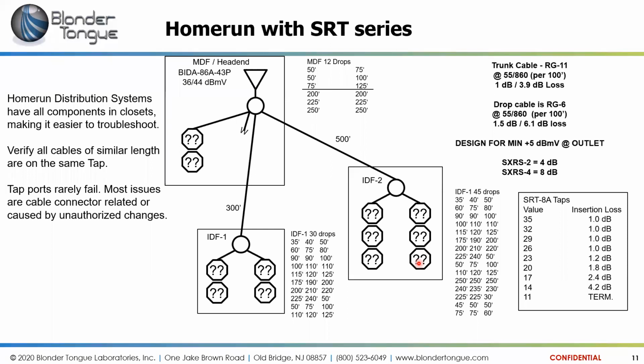For off-air antennas, what are typical RF levels into a pre-amplifier? Oh, with off-air antennas, there is no such thing as typical. I can put up an antenna and put up a second antenna 10 feet away and have levels 20 dB different. I really couldn't answer that as far as what typical levels are into a preamplifier. I will look at the spec of the preamps and tell you what they should be going into a preamplifier in an email, but I can't say what the typical levels are.